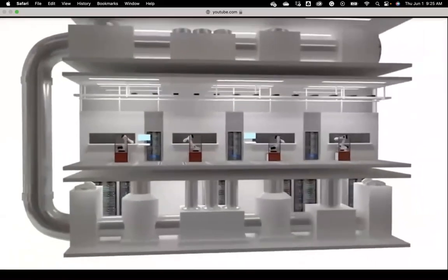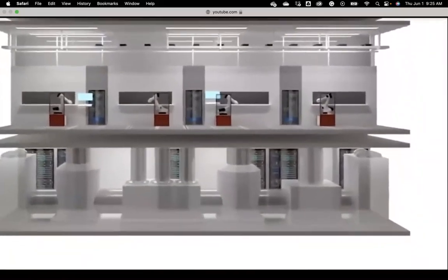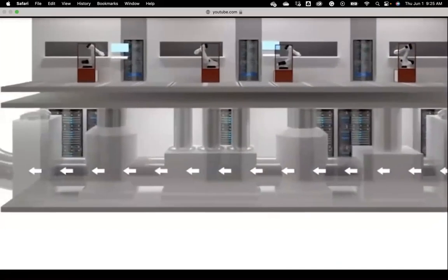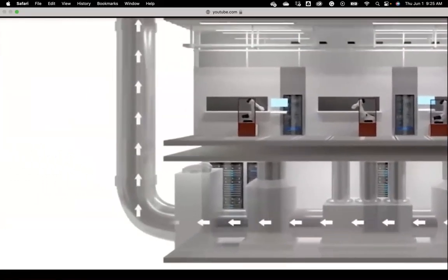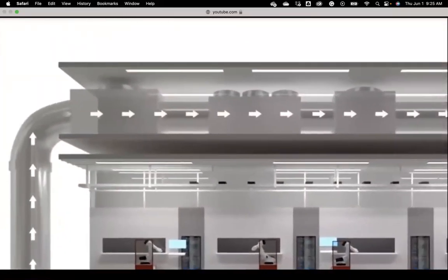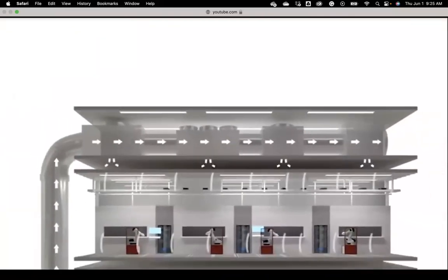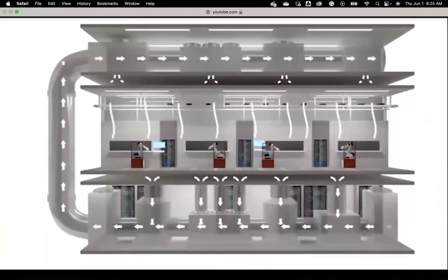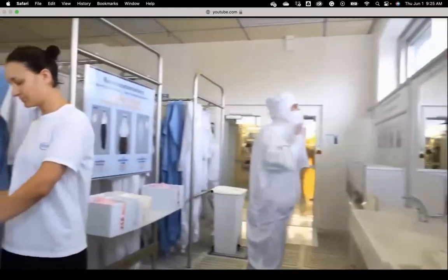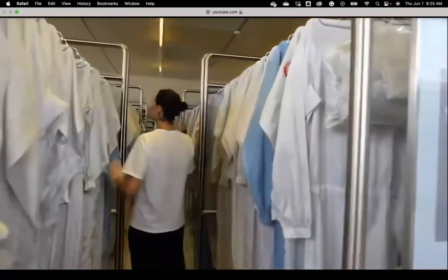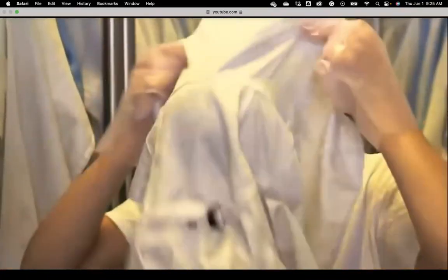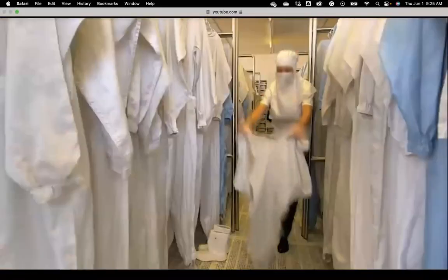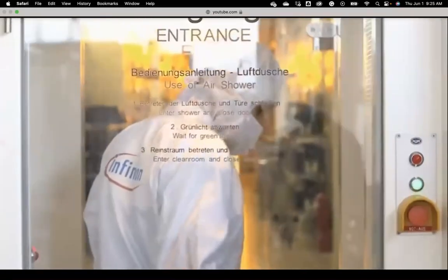The ventilation, filtration, and supply systems in a clean room therefore have to be extremely sophisticated. Several million cubic meters of air are circulated every hour, and hundreds of air volume regulators maintain a constant airflow. Employees in these production areas have to abide by an extremely strict dress code. They are not permitted to smoke before work or wear any makeup or jewelry. Cleanroom production areas can only be accessed through a special airlock.